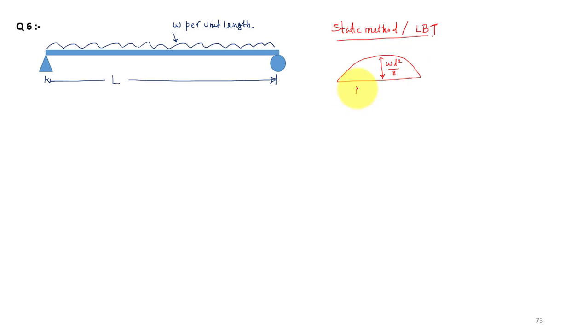So this is my bending moment diagram at maybe elastic state. Now we can draw your bending moment diagram at the plastic state. At the plastic state, what will happen? This peak moment will be reaching your plastic moment. So this will be equal to your moment corresponding to your ultimate loads or the collapse load. So WC L square by 8.